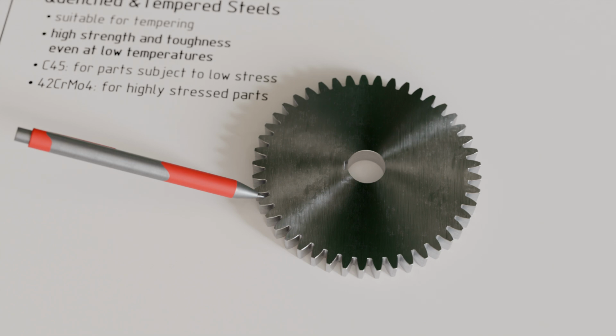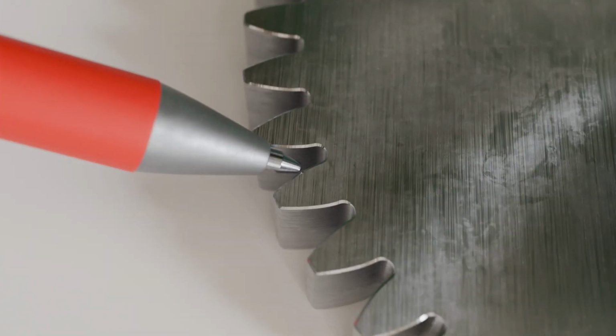This presents a challenge. High toughness requires a low content of brittle carbon. On the other hand, high surface hardness demands a high carbon content. To resolve this contradiction, steels that are suitable for a specific heat treatment, called case hardening, are used. These steels, referred to as case-hardened steels, have a very low carbon content, less than 0.2%, and are, in their untreated state, very tough. In the case hardening process, the steel is exposed to a carbon-rich atmosphere at high temperatures.